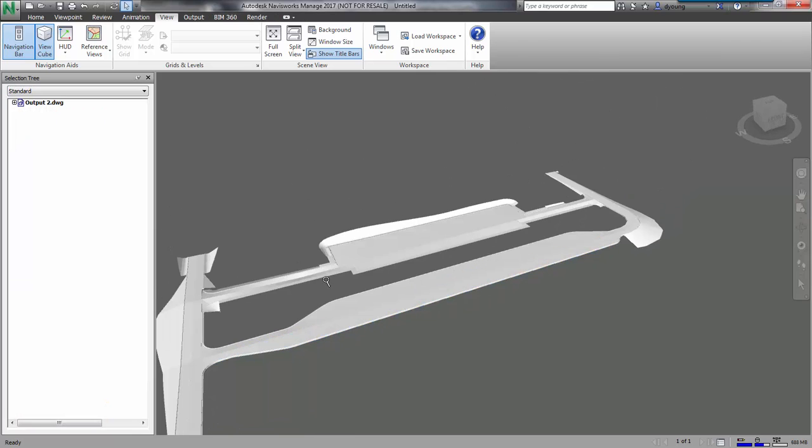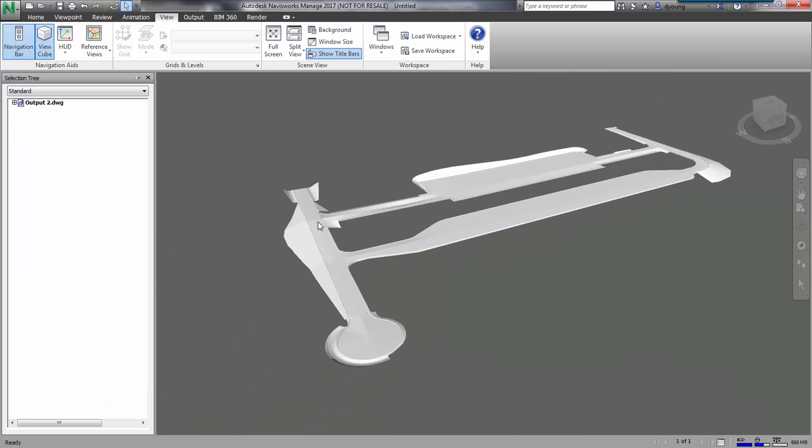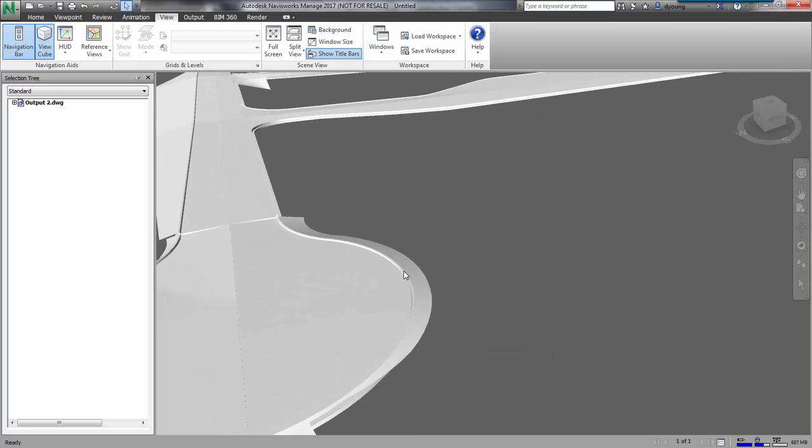So what can I do with this? Well, if I just hover over one of these things, it tells me the corridor name is site plan and the corridor shape volume. I got 83 cubic yards of asphalt or whatever. I could add more information to that. Over here I've got a little curb running around there I could pick. It's got a 345 for a volume. And that's information that was available from Civil 3D, now available in my AutoCAD drawing or even in Navisworks.